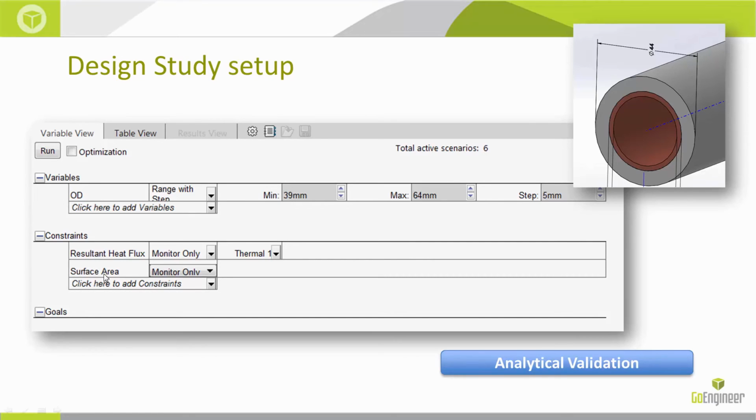Now, with the design optimization tool, I have the ability to stop right here to run just a what-if analysis or set up design of experiments, or I can take this to the next step and specify a goal in order to calculate the thickness that minimizes the heat loss. I haven't done that now because I want to show you some of the post-processing and the graph extraction, how you extract a graph from such a what-if analysis. So I left out the optimization. But let's take a look at what this looks like in the software.